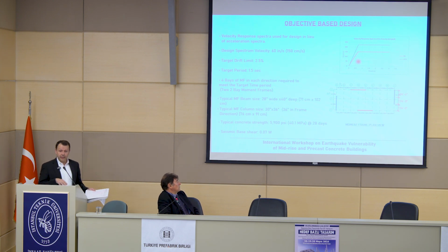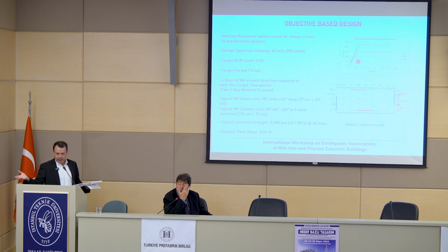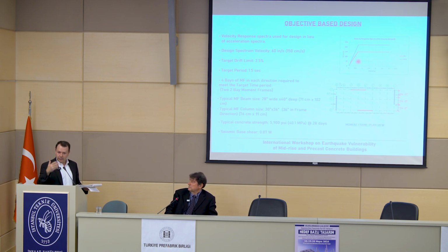One question that I had, so in terms of dimensions, I think we're close in terms of what you were getting. So it's not that we increase the sizes, we can still match the 1% with the initial sizes that were decided based on the portal method. You can also check with your SAP or ETABS model in terms of what those dimensions are and do your checks. But with this idea of having about 1% reinforcing steel ratio for your design.